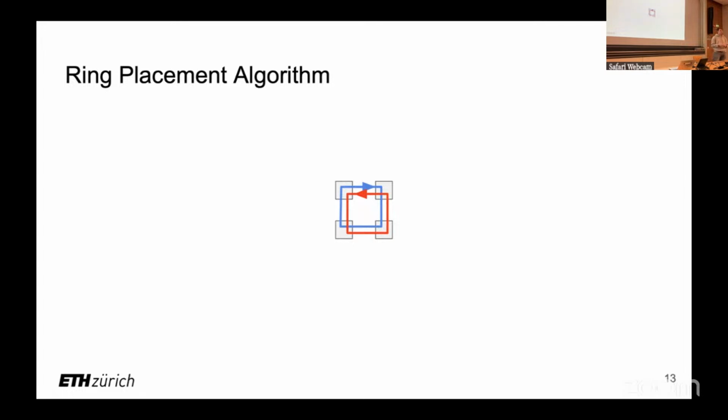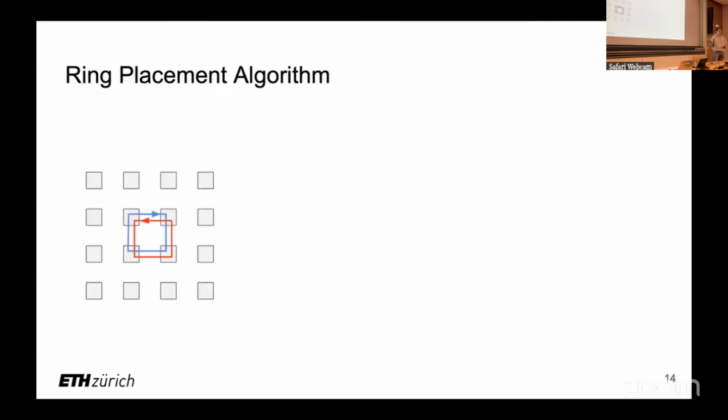Now, obviously, the question is, how do you do this for bigger designs? And so here's where the recursive algorithm comes in. First, you place the design you had one step earlier, hence the recursion, in the middle of your new design. Now, you flip the direction of the loops and rotate your design by 90 degrees. Obviously, for the 2 by 2 design, that does nothing. It's still the same, but it's important for later stages. And now what about the other cores around here that we haven't connected? Well, they introduce new loops to connect them up to all the other cores as well.